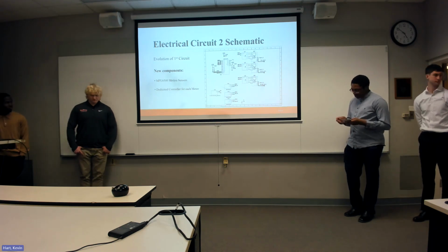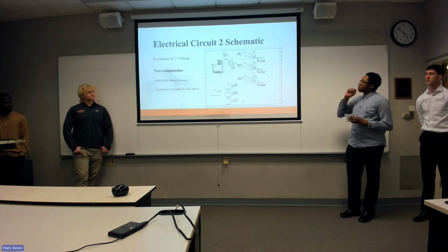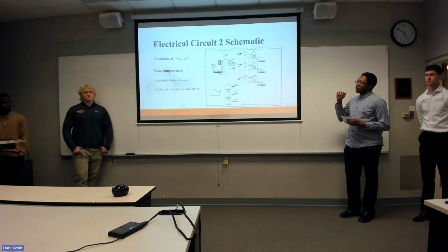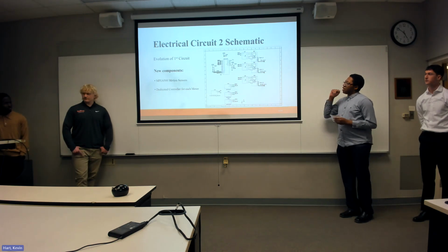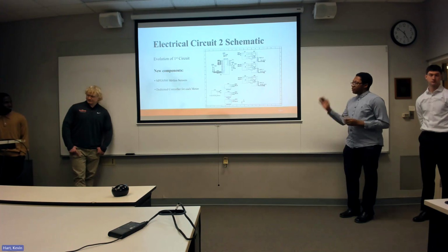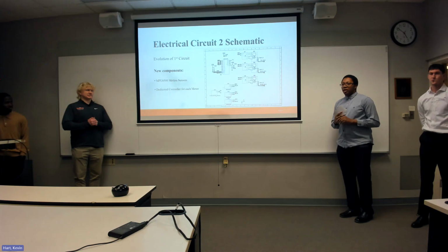And then there's also dedicated controllers for each motor. So the microcontroller would send the step and direction to each controller, and then the controller would send the appropriate analog signals to the motors, which will drive each joint. And then the flex sensor is connected to the analog and digital pins on the microcontroller.